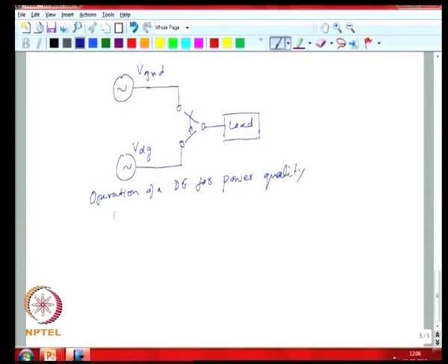You could have say a cold standby, which means that your DG is de-energized and it needs to start up. So, nominally the grid voltage is there. If you need to change over, first you need to start up your source before you can actually transfer over to the source, and this would be typically the way you would run a diesel generator set.